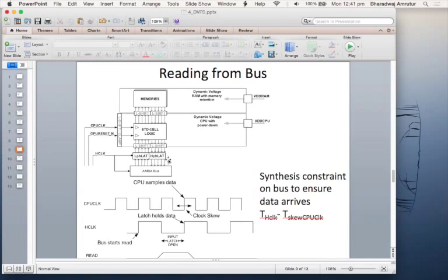where you are using synchronous techniques still to transfer. If you recall, in the last semester we studied how you can have asynchronous interfaces, and you can use one of those techniques also, but asynchronous interfaces add overhead. There's more circuitry and there is more latency to go across, but you can use that and it will work. It just adds overhead, especially in a bus to which the CPU is connected. You kind of want to avoid that because too many cycles are lost.